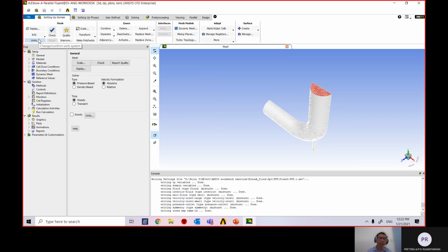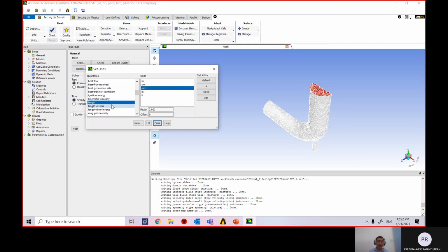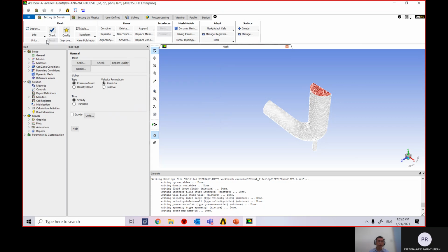So in your notes over there, you just write, remember, once you open the Fluent, go to unit and do setting, go to unit, choose length and change to mm. Just a short note so that later you can follow up.